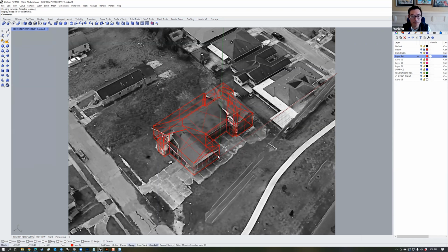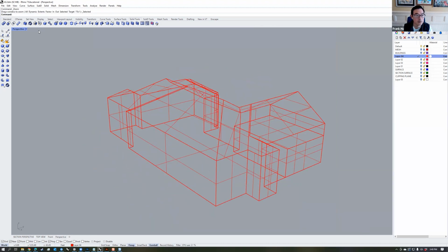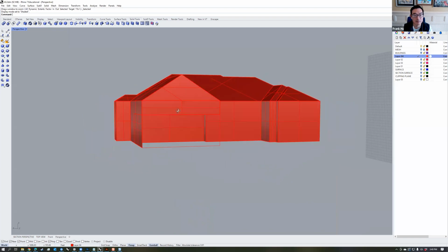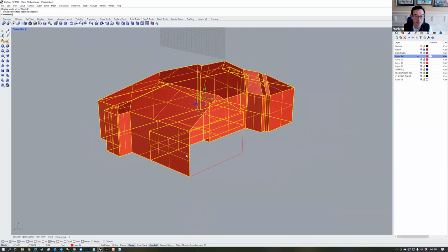If you want to get, for instance, the little porch in there, you can use a tool called wire cut, and you can begin to slice through it. So here's how that would work. Draw a box on that plane there, that porch there. And then you click on that, then you choose the wire cut tool, then choose this as the object to cut, then choose enter. Then you can actually cut into the building like that, and then hit enter and turn on a shaded view. You're beginning to now modify and edit the building slowly.